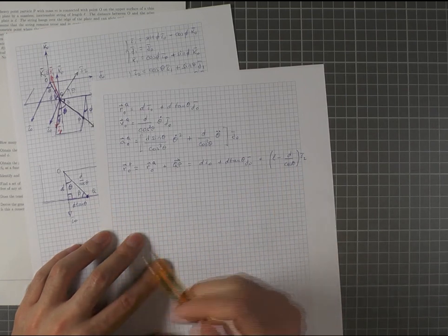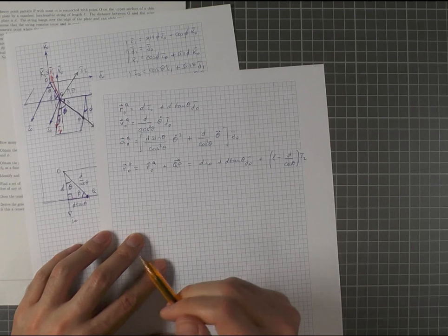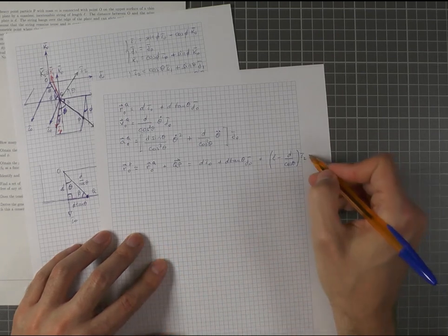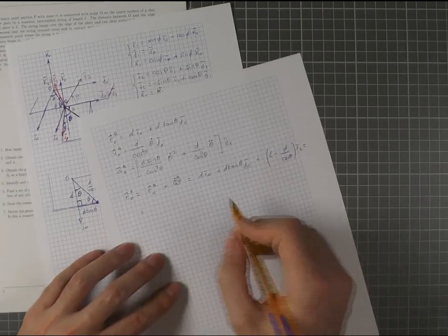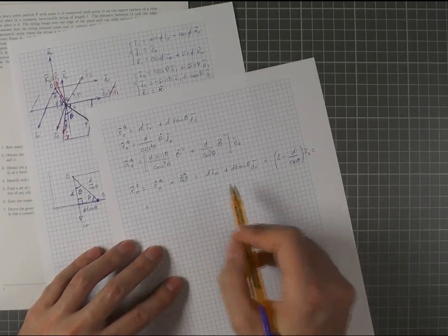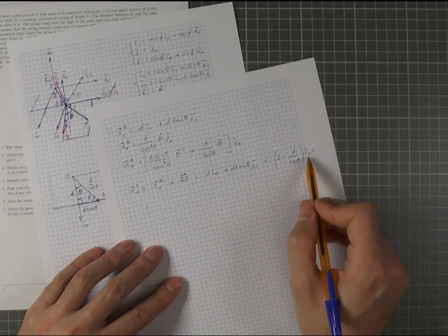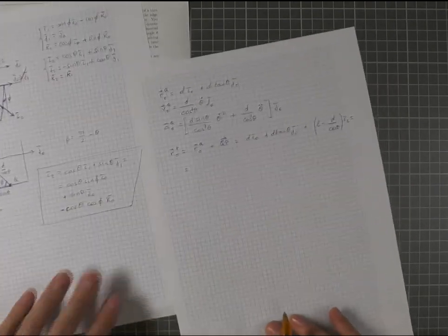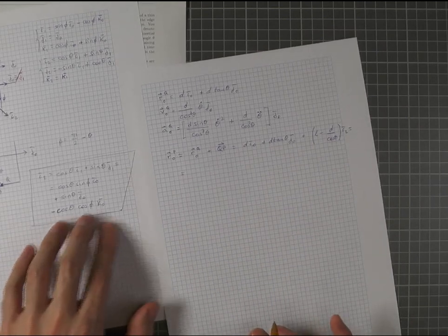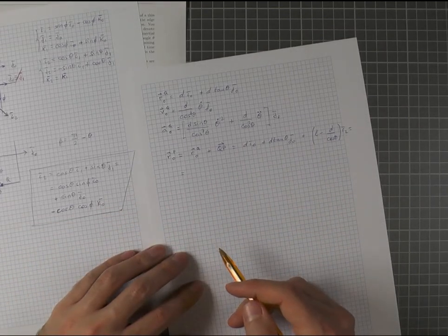So I would need to apply the Coriolis theorem to compute the vector derivatives correctly. The first part of the expression remains unchanged because it is already in basis 0. I just have to transform vector I2. I already have the correct expression here, so I just need to plug this in place of I2.